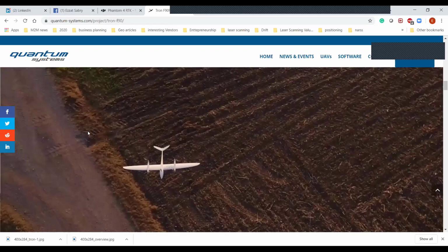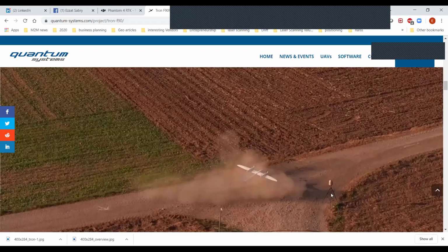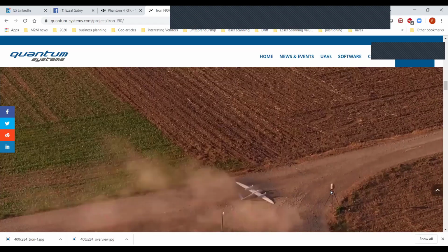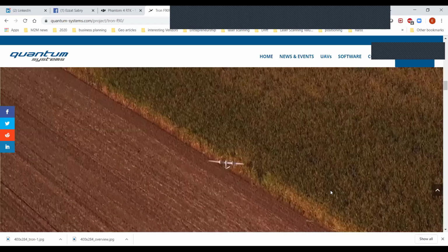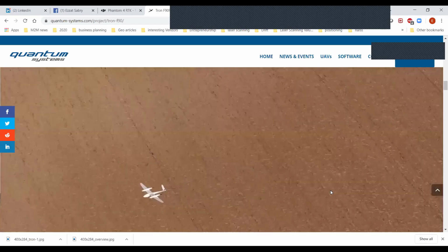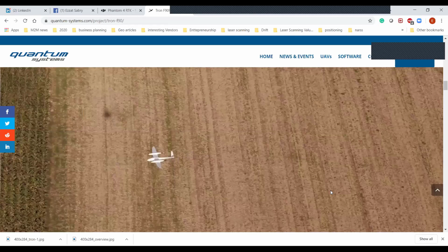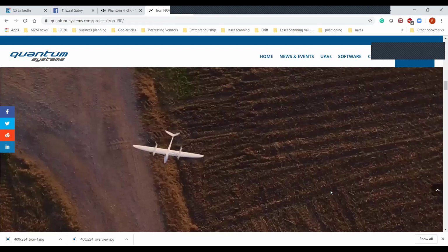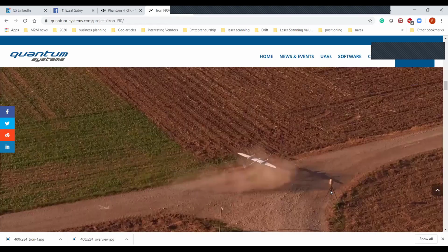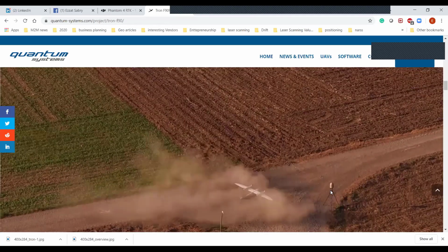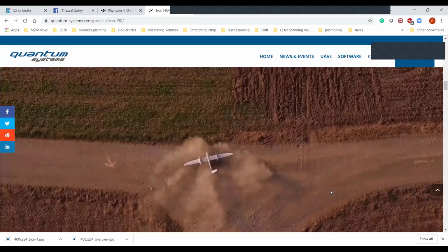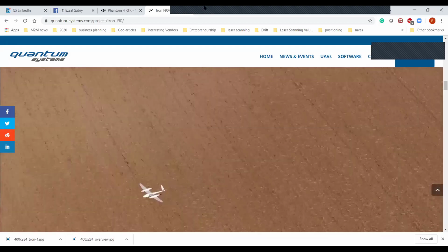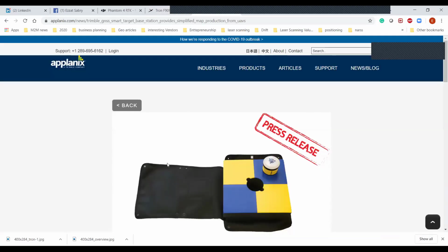One of the interesting points is that here we have to use only one base station, but because we are using RTK and PPK technologies, sometimes we need to check ourselves. We need to know whether we are still getting the accuracies we are expecting, or there's something wrong. So I need to take some ground control points to check my accuracy and to get a better feel of what is going on in the project.